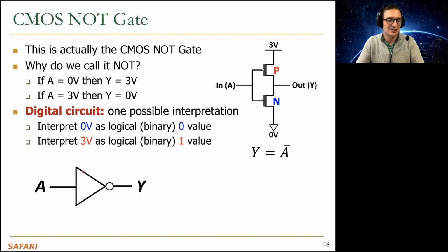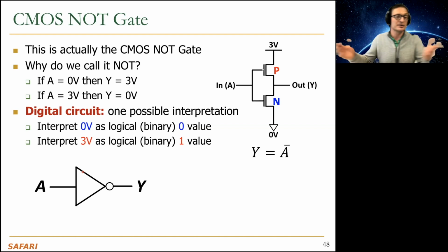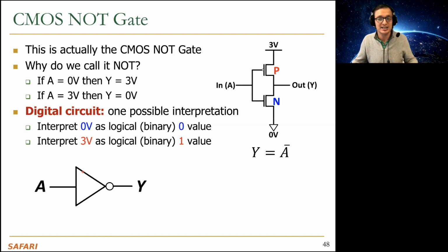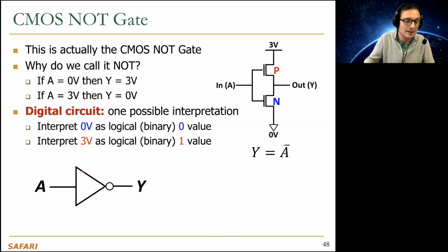So as you mentioned, okay, we're going a little bit into the lower level. How do you keep voltage always at 3 volts or 0 volts? That's actually a challenge also, because you don't have perfect circuitry, right? As voltage travels over the wires, it gets lost. You may actually lose voltage for very different reasons. It may become 2.8, 2.4, 2.2, 2.1. And at some point, you may need to amplify the voltage. And the way to amplify the voltage is by having buffers, for example, or double inverters potentially, right? At the right places, at the right times. Of course, you need to do the sizing of those transistors very carefully, etc.